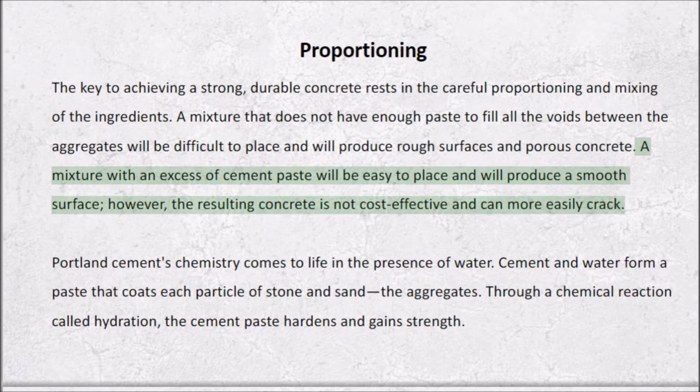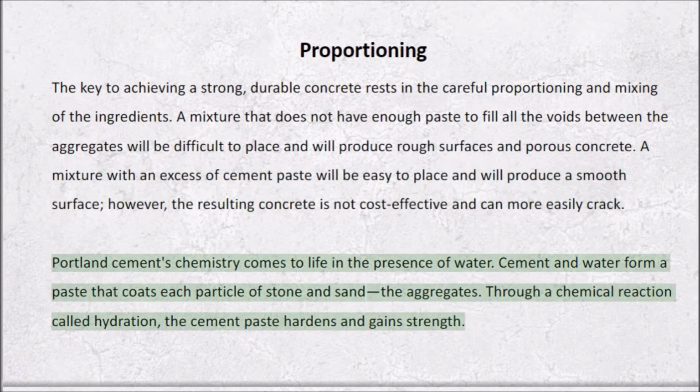A mixture with an excess of cement paste will be easy to place and will produce a smooth surface. However, the resulting concrete is not cost-effective and can more easily crack. Portland cement's chemistry comes to life in the presence of water. Cement and water form a paste that coats each particle of stone and sand, the aggregates. Through a chemical reaction called hydration, the cement paste hardens and gains strength.